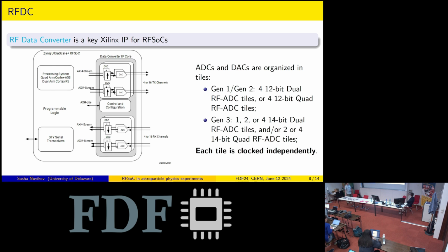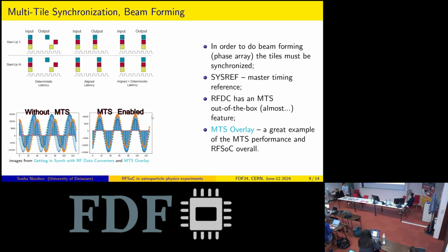But for us, it's actually a problem, because when we want to do beamforming, we want everything to be synchronized very well, and having each block clocked independently is actually a little bit of an obstacle for us. However, Xilinx has this feature called multi-tile synchronization, which again is super useful for beamforming, which is one of the most essential ideas for the experiments I just mentioned.